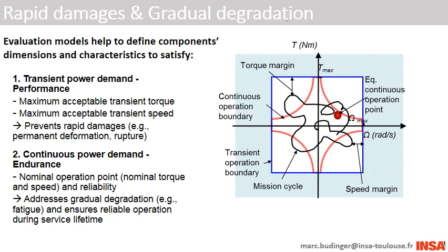Continuous or repetitive power demands. In that case, we will talk about endurance or durability, and we will make sure that the fatigue torque or speed don't exceed acceptable limits. Here, the objective is to determine a certain lifetime in case of progressive degradations.